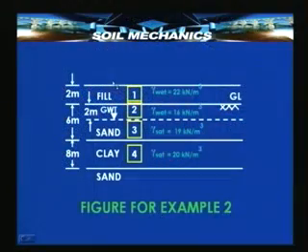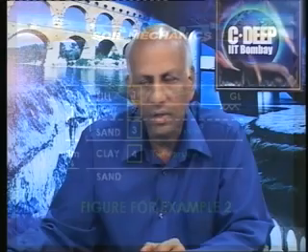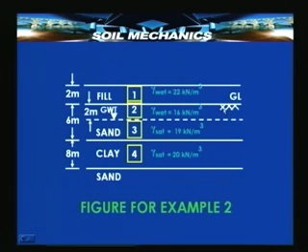Now, further we have one more detail added here, that is, the groundwater table is not right up to the top of the ground surface, but it is 2 meters below the original ground level. That means, a 2 meter part of this sand layer at its top is just moist or wet, but not saturated, and the fill layer which is above is also moist or wet, because it has been compacted by adding water to it.